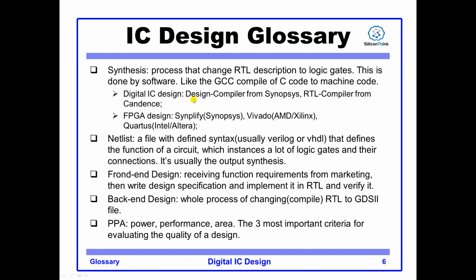For IC design, you have to use Design Compiler, or RTL Compiler, or some other tools to do the synthesis. For FPGA design, you have to use Synplify, Vivado, or Quartus to do the same job. This process is more like the GCC compile process of C code.